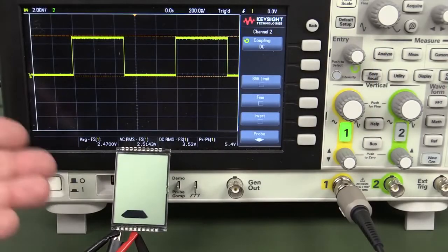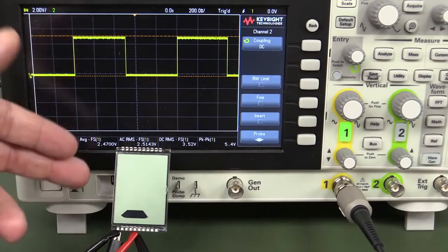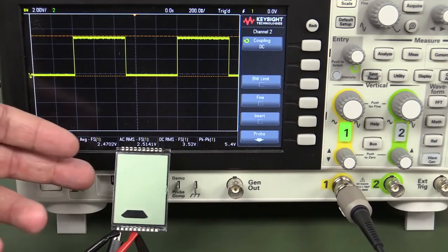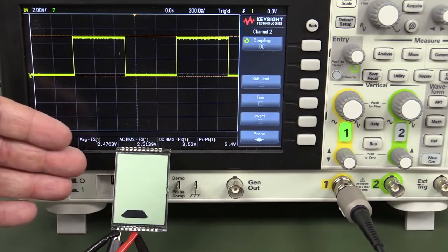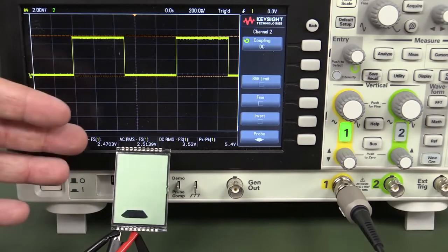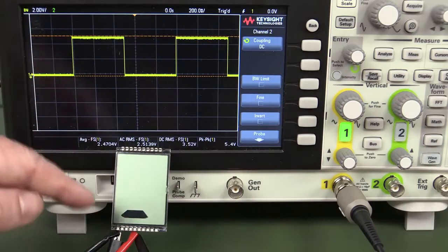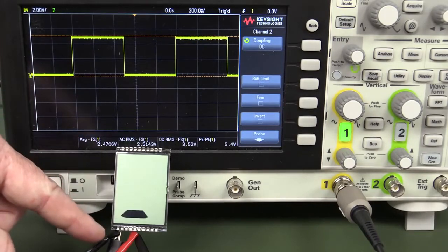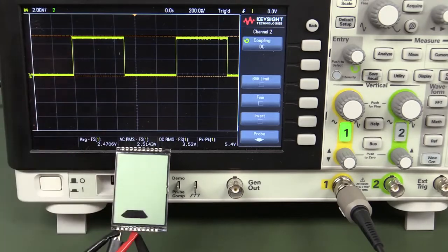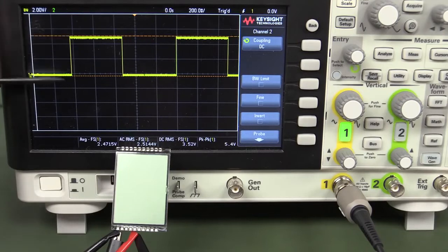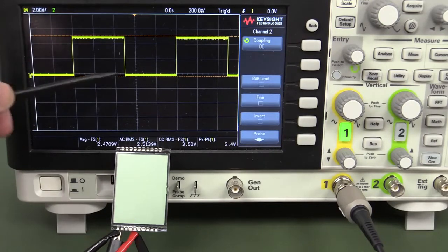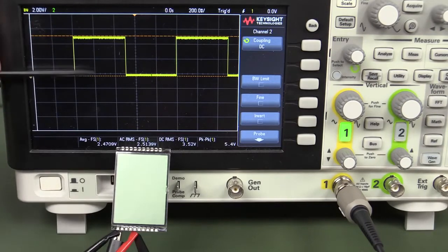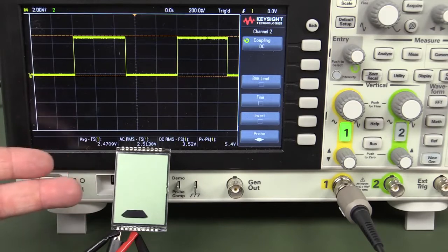So let's use the example of this same 7-segment LCD that we used in the previous video. I'll link in the datasheet down below. It's a nominal 5 volt drive static display, which means it only has the one common pin, which is down in the bottom left corner there, and we're just driving one of the segments here, 2 volts per division with a 5 volt TTL signal there, 1 hertz on, off, on, off, on, off, simple like that, and our ground reference point is there. And as you can see, that works just beautifully.